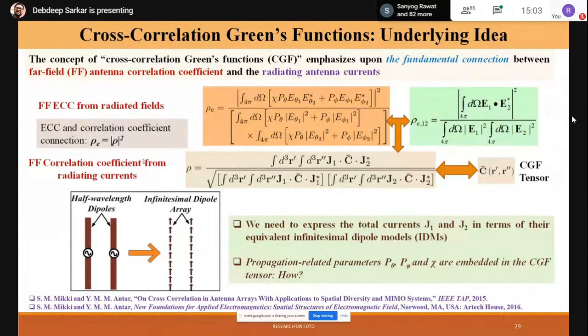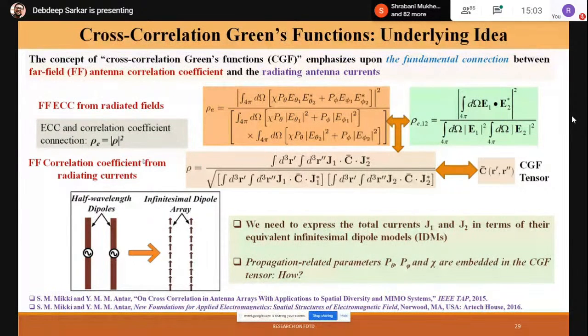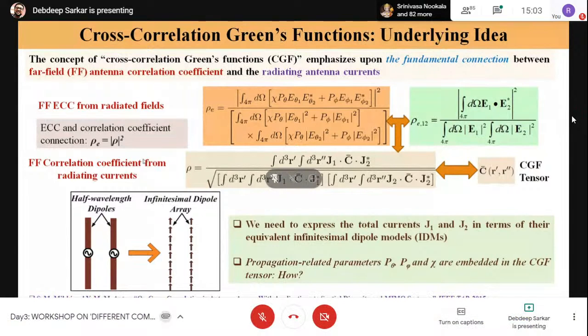The general idea is, whenever you find any unknown current distribution in space-time, let's say you have a sheet of current, or a dipole antenna, wire antenna, or a printed patch antenna, you can discretize the radiating current in that system in the form of small infinitesimal dipoles. You can estimate the radiation from that patch or slot by a combination of small infinitesimal dipoles located at certain locations, and some optimization routines you can use.